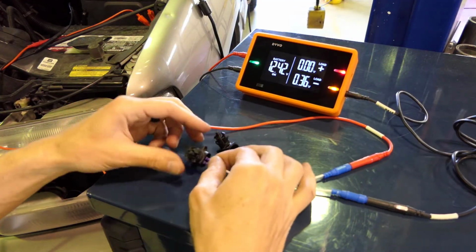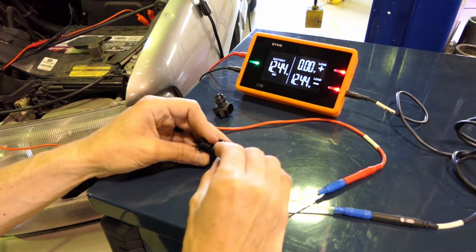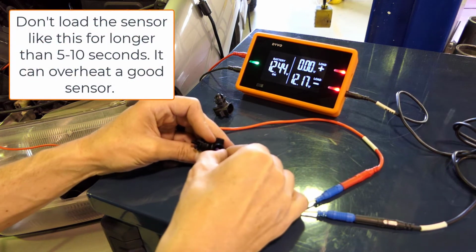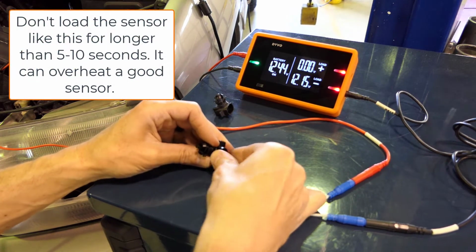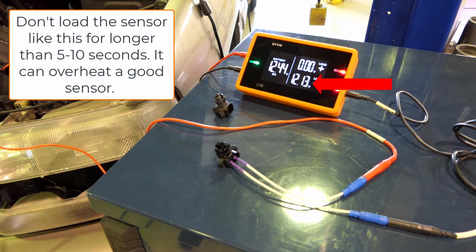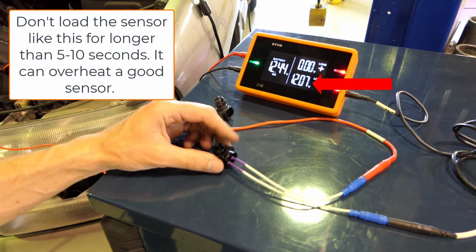Let's connect this to our new temperature sensor and see how it's different. Now look at how the value on that temperature sensor is dropping very, very slightly, nowhere near what the other one was dropping. It's clear that this temperature sensor is defective. You can see what a good one looks like.